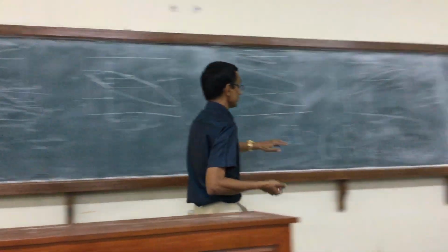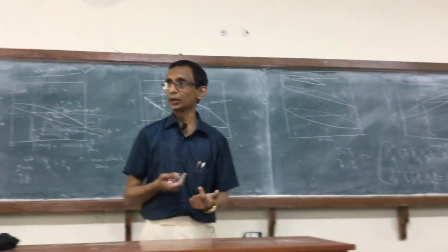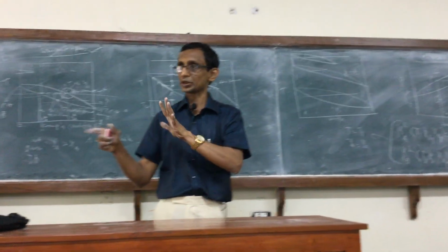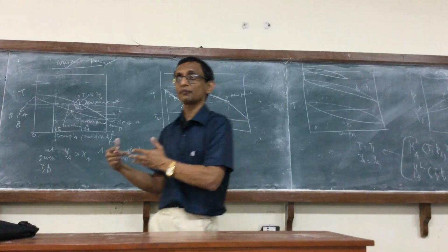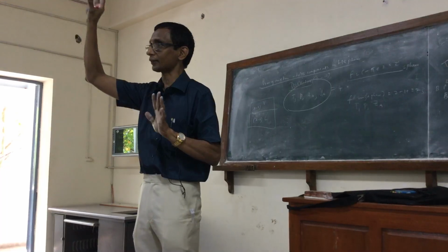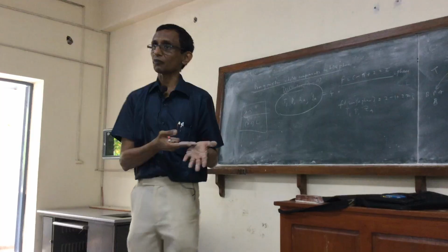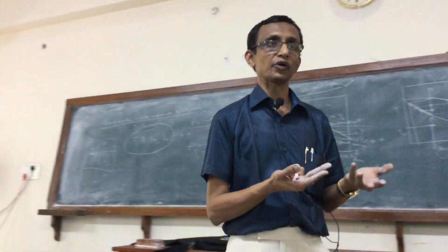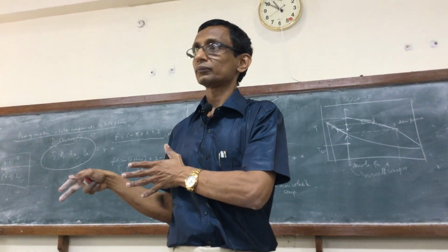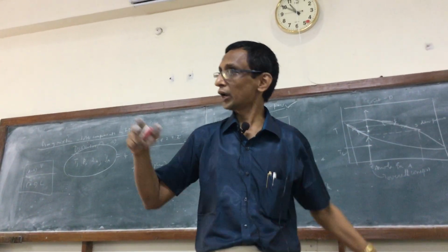Now we are having equations in temperature and YA. Earlier, it was an equation in XA and YA. Derived from the same basic equation, but for each set, the equations that we have to solve are clearly different. They are completely different sets of equations, derived from the basic source. Once you have to solve for T and XA, or for P and YA, the equations will obviously be different, because what you fix determines the actual equation that you are going to solve. All the 6 sets of equations can be obtained from the basic set, but for each specification they will be different,